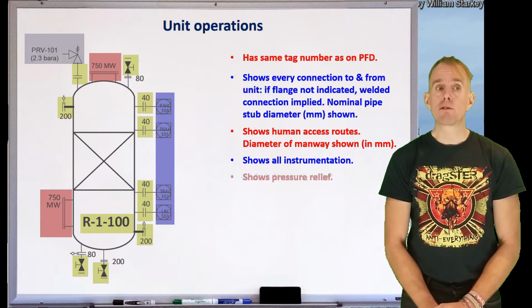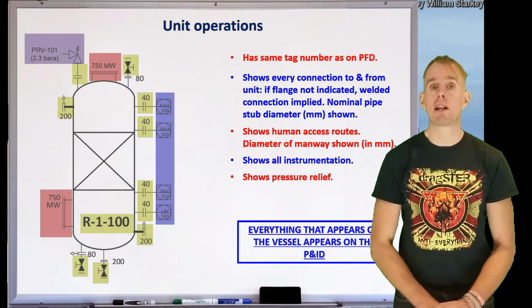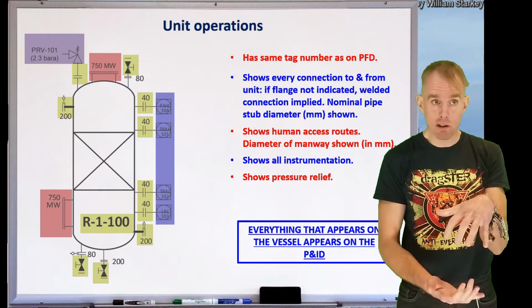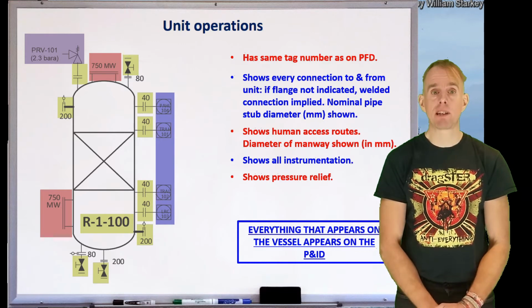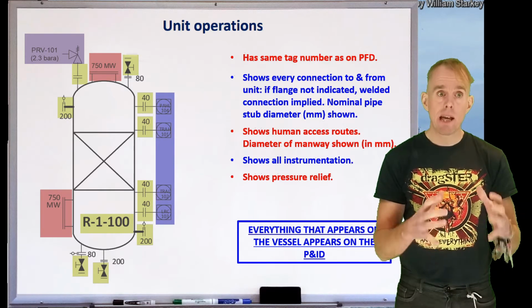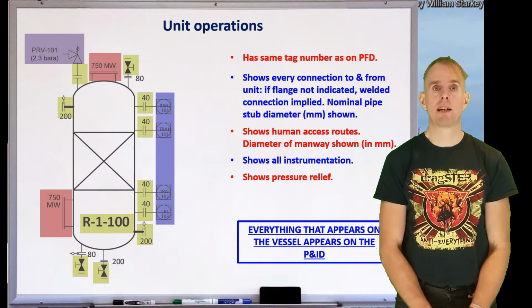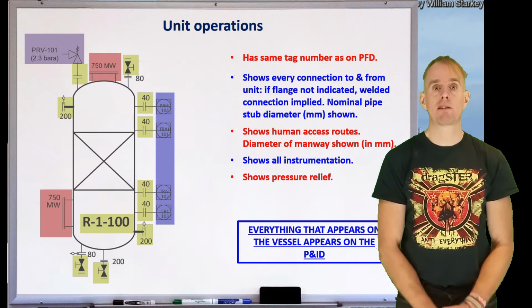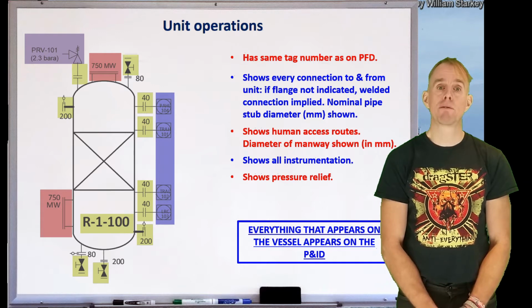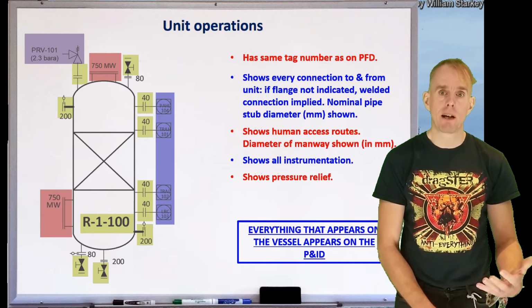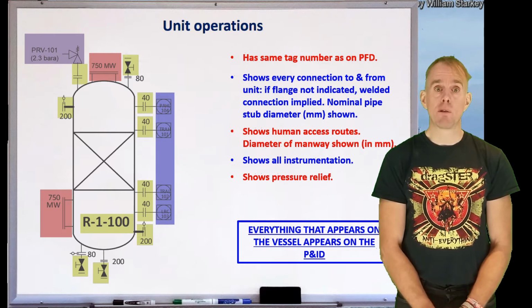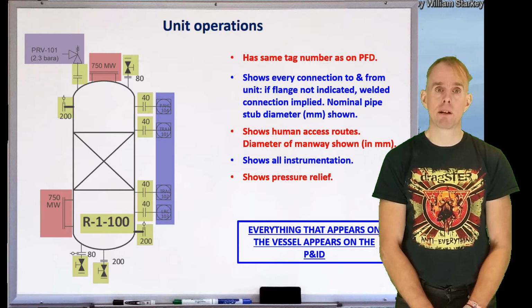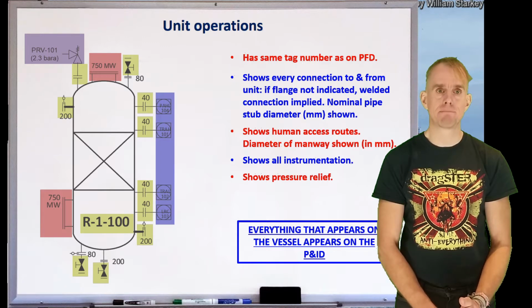The final thing I'd like to draw your attention to is this pressure relief valve on the top left of the vessel. Again, it is bolted onto a flange, and your pressure relief valve is a key piece of safety equipment. If the pressure inside the vessel exceeds a certain threshold, this valve will lift, getting rid of any excess pressure build-up, which could prevent catastrophic vessel fracture in case of overpressure. We've also included here the pressure at which this relief valve lifts, 2.3 bar.